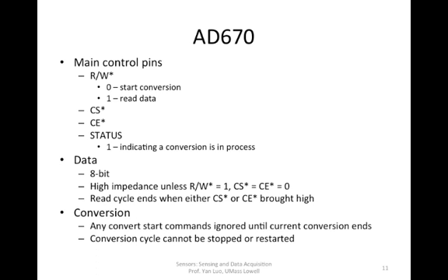What if one is outputting 0, the other one is outputting 1? Right? It's going to cause corruption of the signals. So this high impedance will make sure that if this chip is not instructed to talk, it should not talk. It should not be outputting any signals. In other words, it should keep itself in high impedance mode so that other components can output signals.